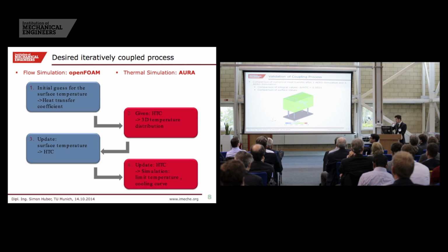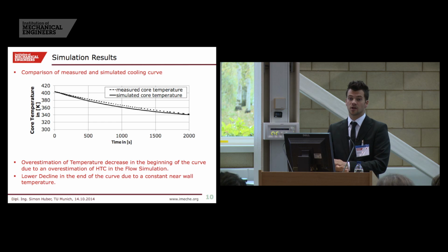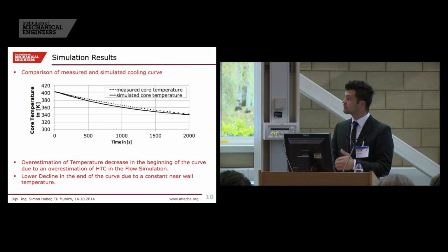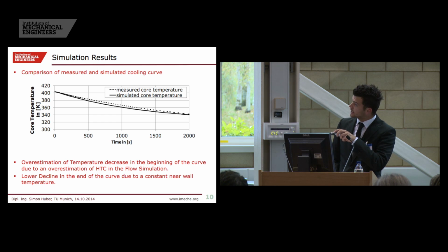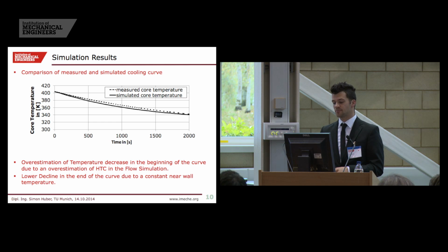Now I would like to simulate cooling curves and compare them with wind tunnel results. You can see here the solid line is the experimental curve out of the wind tunnel at the Technical University in Munich, and the dotted line is the cooling curve from the coupling process with the scalar DES model. And we can see here, in the beginning, the temperature decrease is a little bit overestimated, but in the end the curves fit quite well.